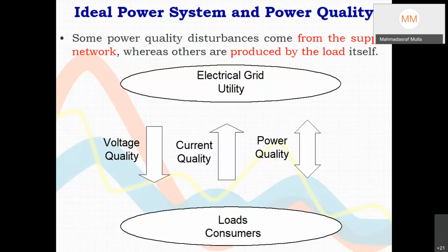Each transformer or generator has some small source impedance. Subtracting a non-sinusoidal current drop across that reactor from the sine voltage results in a PCC voltage where small harmonics will always be present.